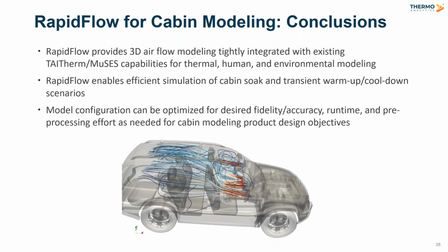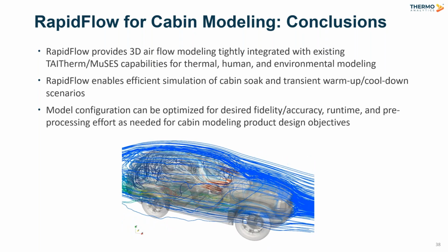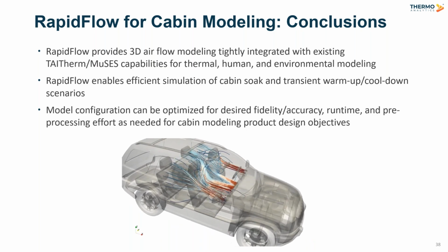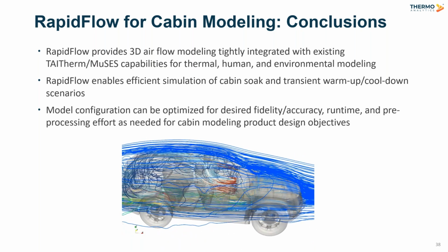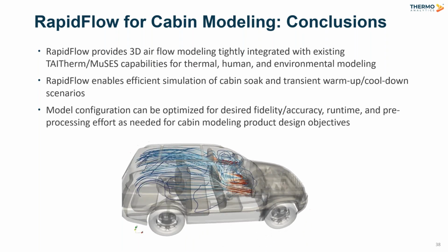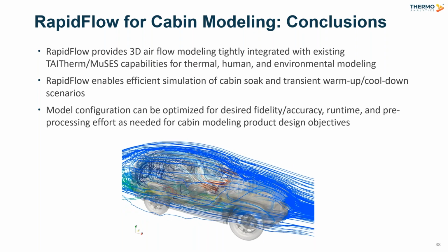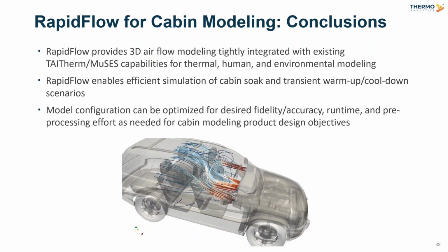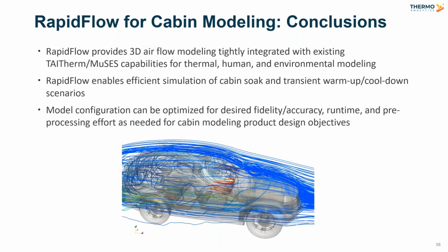So if you wanted to prescribe the split, you could have both of the outlets, or even more than two, all be inlets and just specify the outflow for each one. Or you could specify the outlet for one of them and have the remainder be pressure outlets and just allow them to solve for what comes out. But you've got flexibility on whether the outlets are calculated or prescribed is what it comes down to.